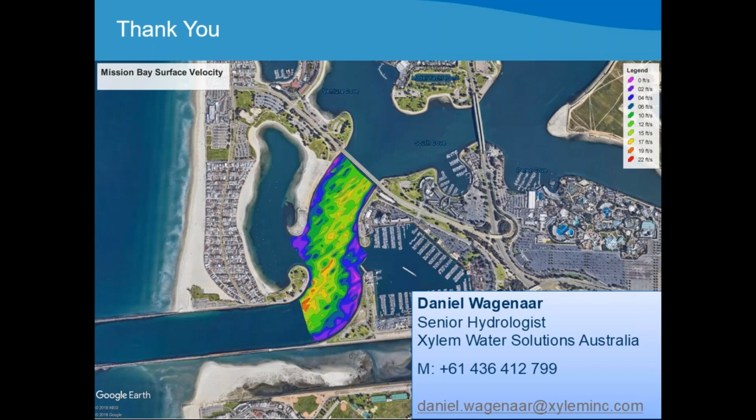Daniel, if you use the USGS option in RiverSurveyor, does it detect if it's an S5 or an M9 and set the blanking distances accordingly? Yes, RiverSurveyor Live automatically detects if it's an M9 or S5, and based on that will apply the screening distance. Just to confirm again, irrespective of whether you use the USGS version or the standard version, if you use the standard version, you can go and type in the manual distance as well. But it does detect that for the S5s, and the same with QRev. That information is populated in the MATLAB files and then available to QRev. So QRev knows automatically if this is an S5 or M9.